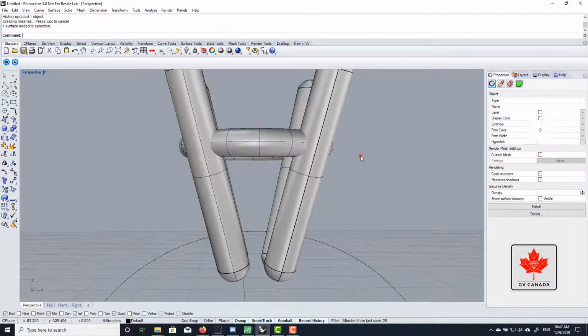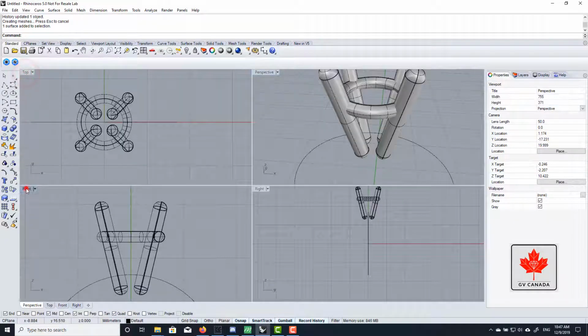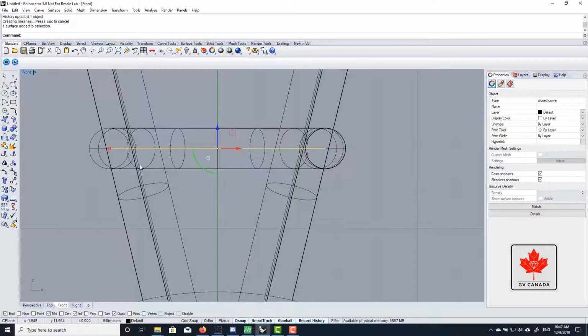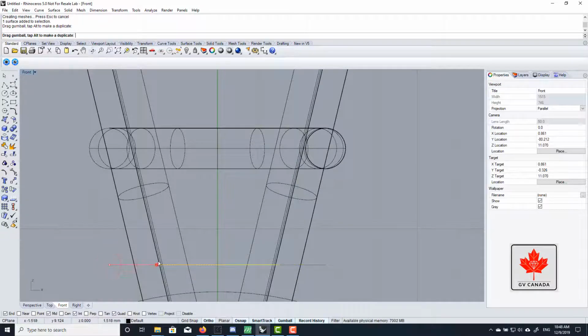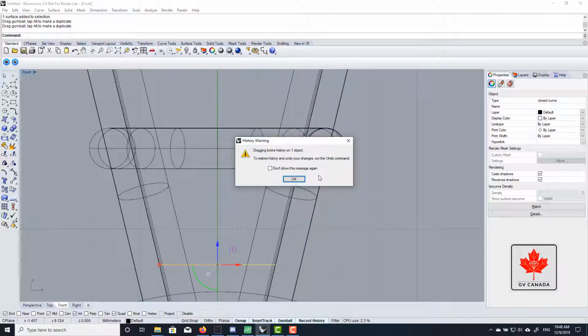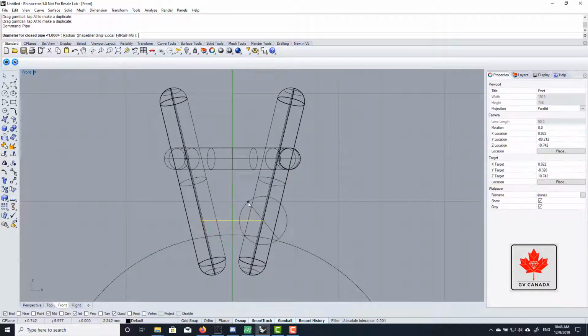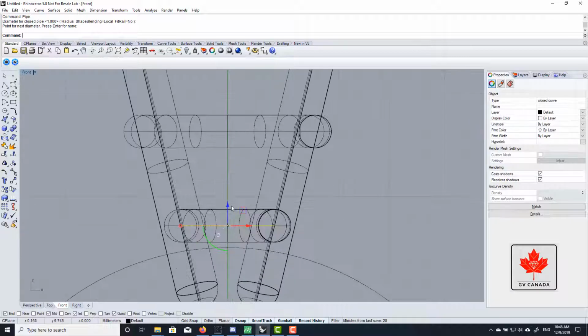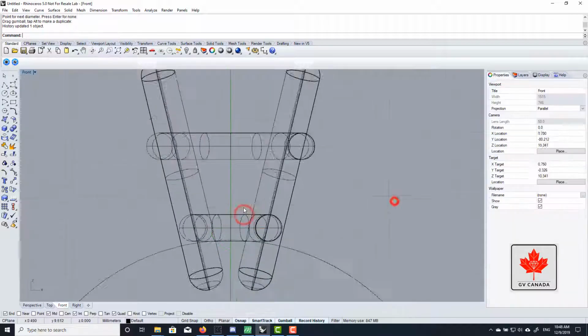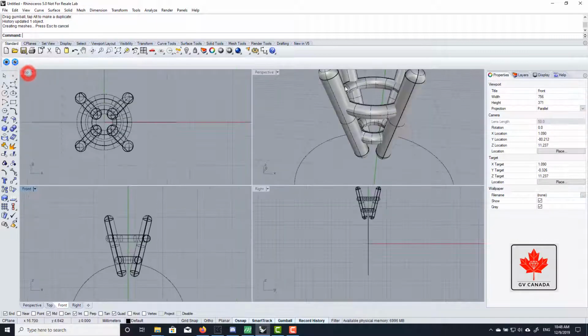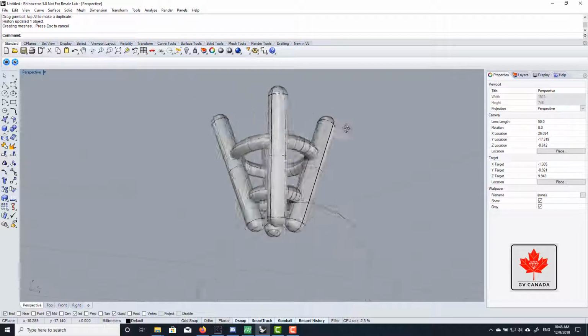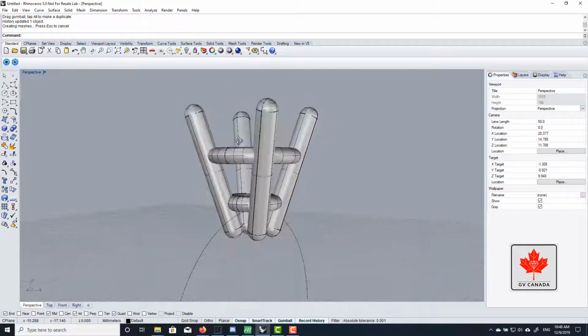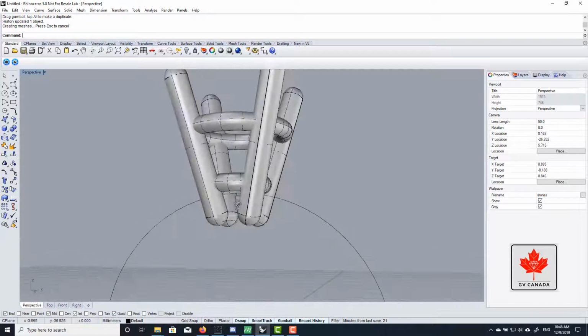I'm going to make another one below it. So what I can do is grab my circle curve here, click on the arrow while holding Alt on the keyboard. I'm going to click on the arrow and drag down. I'm going to use the scale, hold Shift, scale this inwards since this prong arrow is down at the bottom, and I'm going to type pipe again, 1mm. So now we have our first setting. Okay. And again, we'll cut this out after we've created the shank.